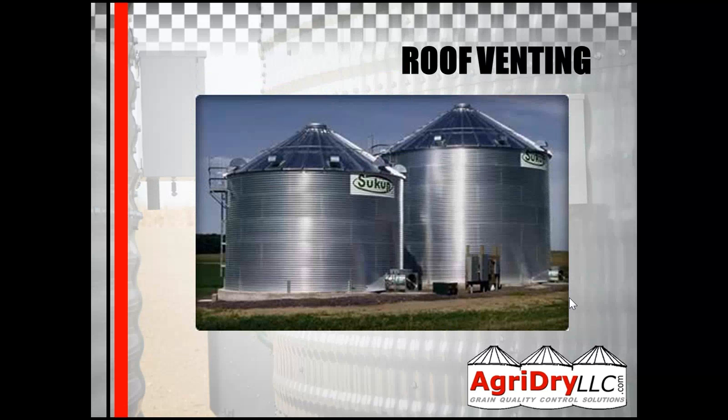So roof venting. This is pretty typical across the Midwest. A lot of the roof vents are down by the eave or somewhere close to the eave and evenly spaced around the bin itself. All right. The biggest thing with roof vents is the air that you're pushing in from the bottom is going to tunnel to wherever the air can escape out the top. So wherever those roof vents are at the top, that's where the moisture is going to change in that grain mass.